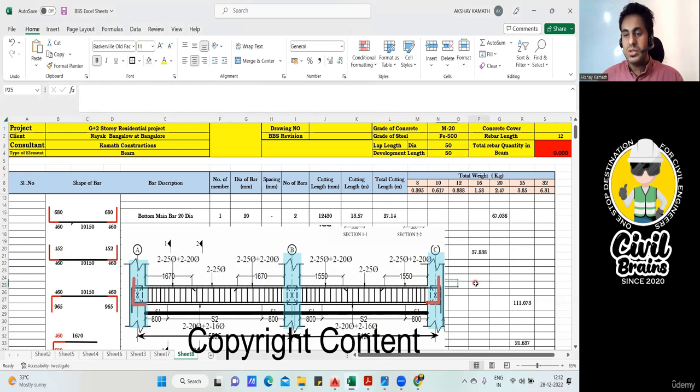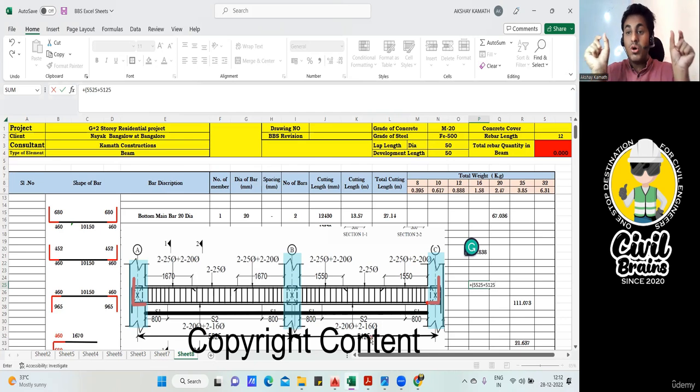So observe here. I'll open the bracket on the Excel sheet. What is this center to center? From this center to this center, it is 5525. I'll write 5525 plus, again I'll add this center to this center: 5125. So I got from center to center. I'm telling you from inner to inner I require, that is called the clear span.